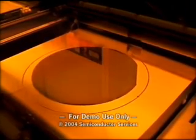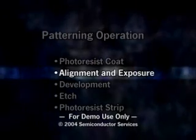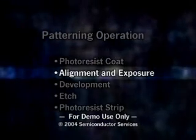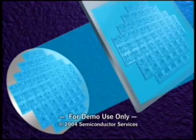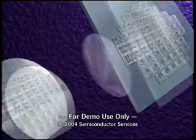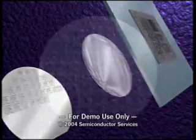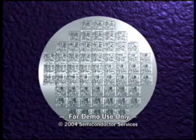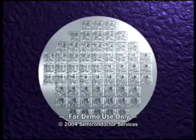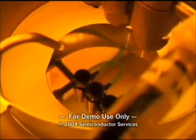photoresist solvents. In step 2, the critical alignment and exposure procedure, the pattern on a reticle or photomask is aligned to the wafer, and then transferred into the photoresist layer using one of several different approaches. After alignment and exposure, the photoresist layer has regions of exposed and unexposed resist. Bringing out the pattern in the resist layer occurs during the development process.